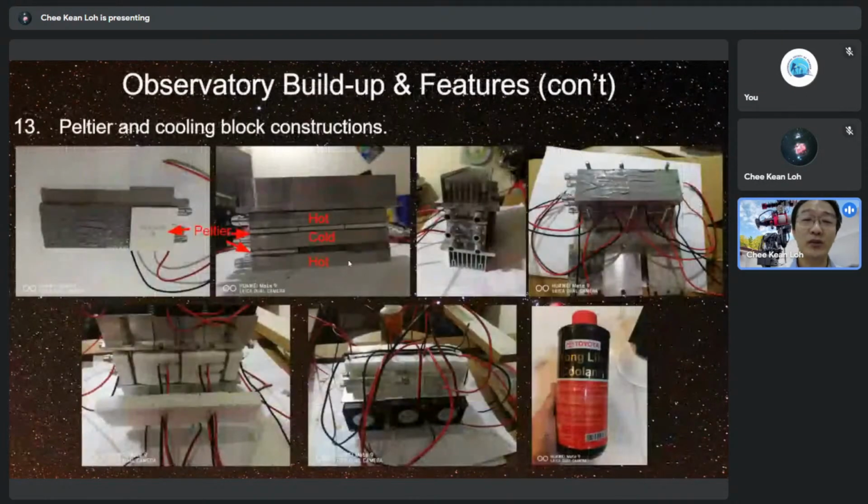Oh, okay. So one more thing, just to take note, the Peltier is a very sensitive device, module. So if you happen to buy one and you start to pump in 12 volt and maybe whatever ampere, right? Then it starts to heat up and one side will be hot, one side will be cold, right? If you don't have a heatsink around it, don't test for very long.